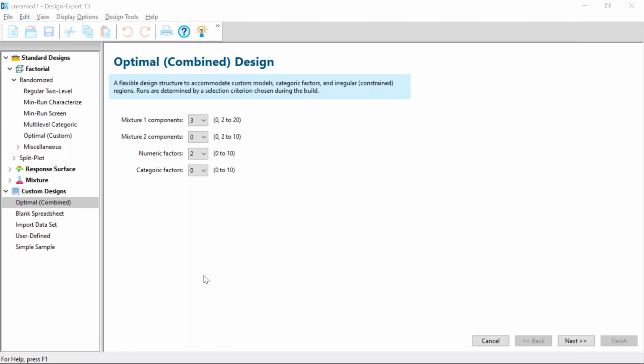And if curvature is not significant, you'll end up with a lot fewer runs, starting off with the factorial design with center points. If the curvature is significant, you can use Design Expert's augment tool to then augment the design in a second block. And so that would be a better strategy of experimentation that allows you to possibly save quite a bit of time, straight away.